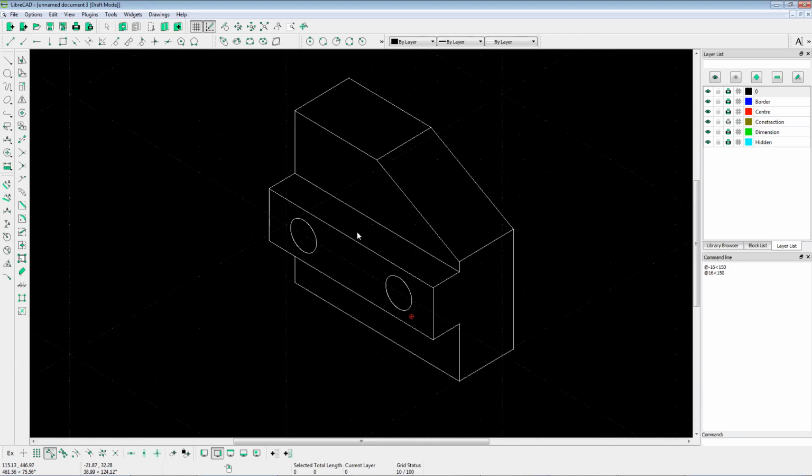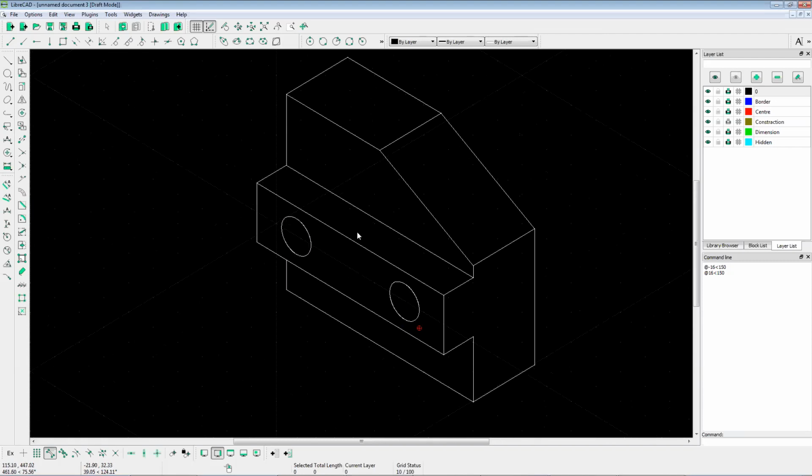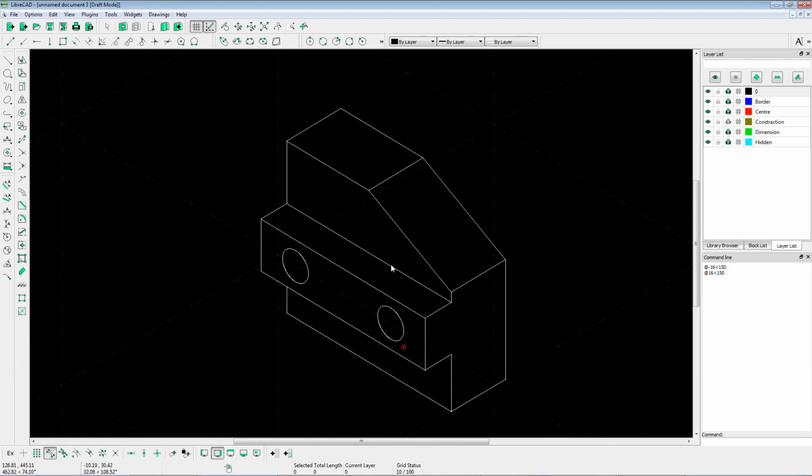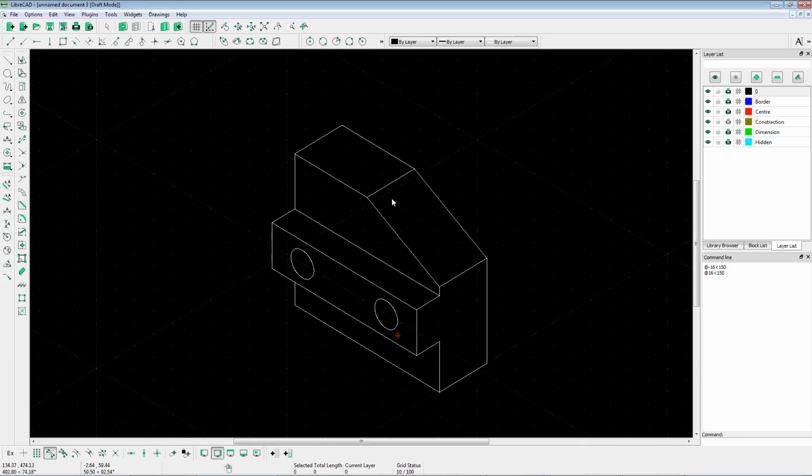Okay. So this is the final shape of the 3D solid drawing of this object. As you can see now, this is what the 2D views details give us as an idea. To make sure your drawing is correct or wrong, you simply draw the views back again. So imagine you're looking from the front view, and you draw a front view from there, and then the side view, and then the top view.